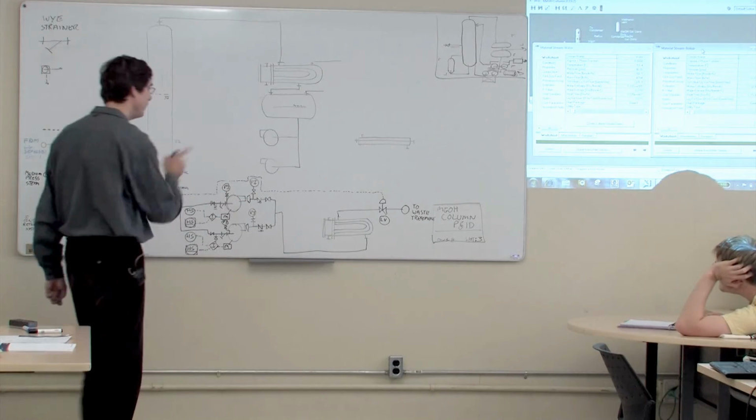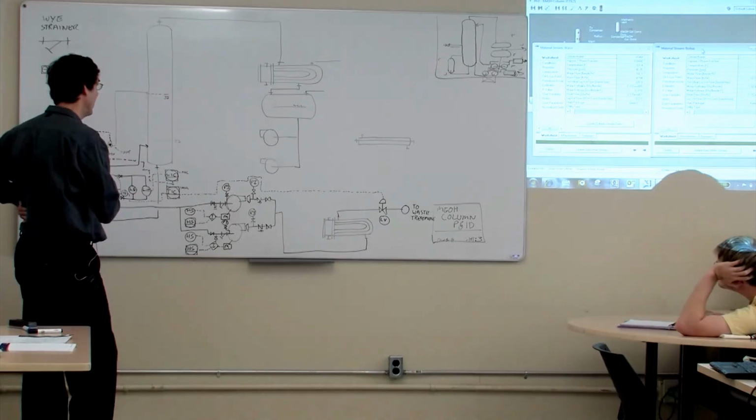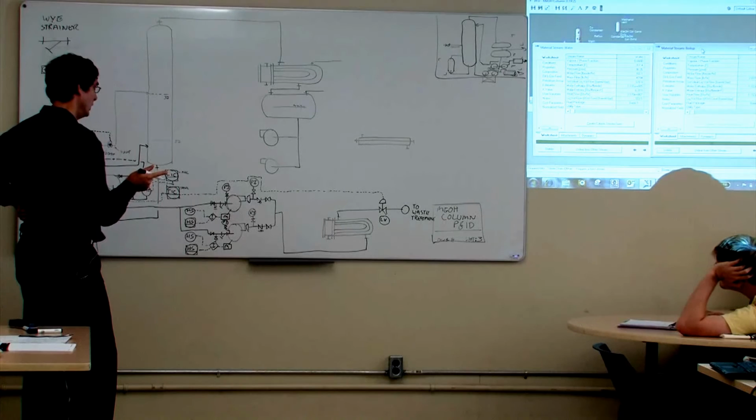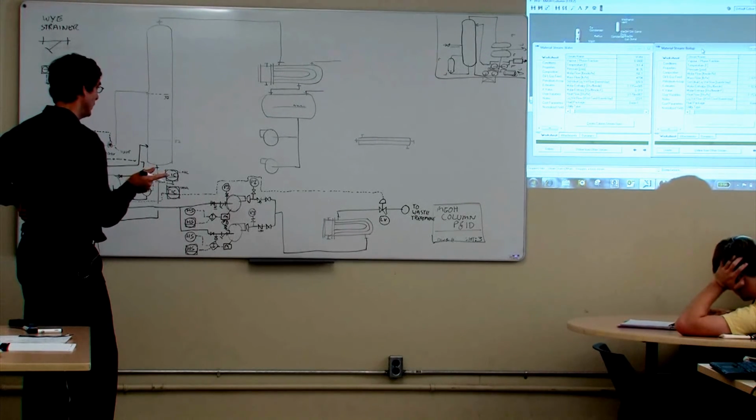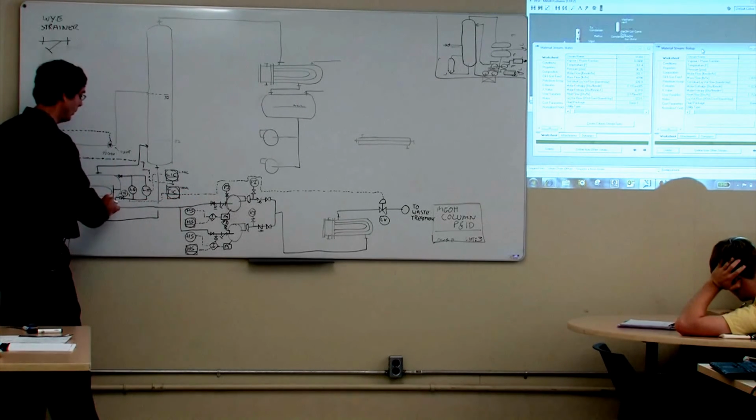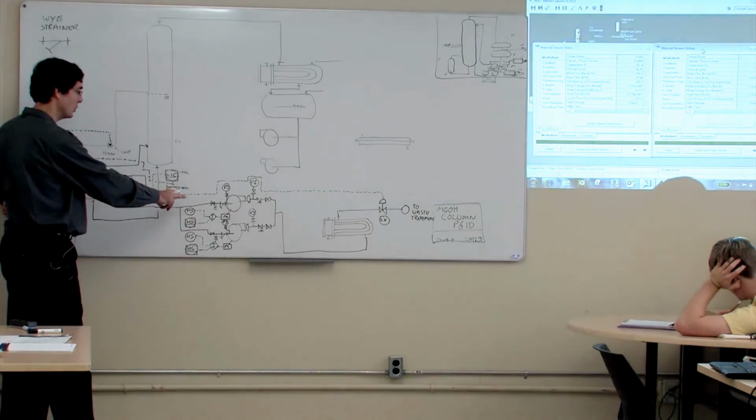Okay, I haven't decided what my failure position is on that valve yet. So, do I want to dump the contents down into the waste treatment facility, and possibly the pressure could be a problem? Actually, what could be more of a problem is I could end up emptying the liquid level and sending two phases into the pumps.